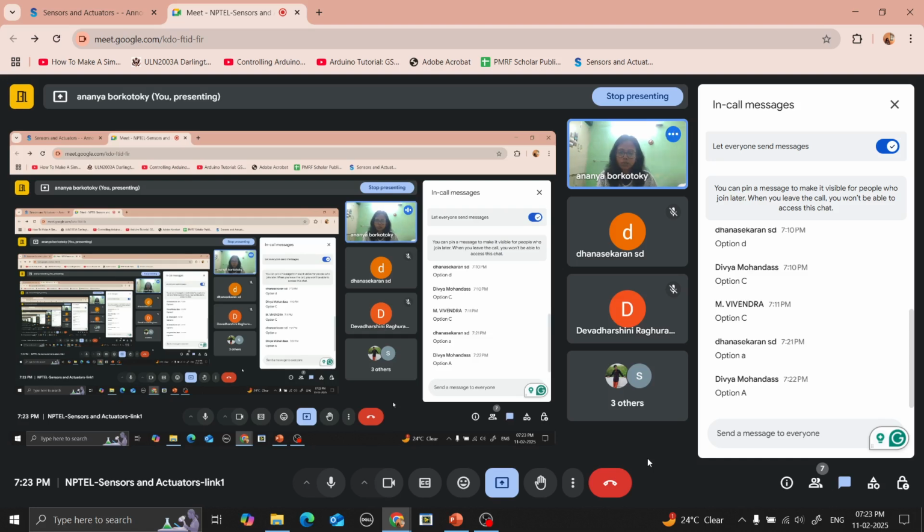SiO2, so most of our sensors we make on a silicon substrate. The reason is that silicon is easily available, there are other advantages of using silicon, and we already know the fabrication process, the photolithography and etching of different materials on top of silicon. So these are well known. For other substrates we also use PDMS or glass in case of microfluidic devices, but silicon is most commonly used.